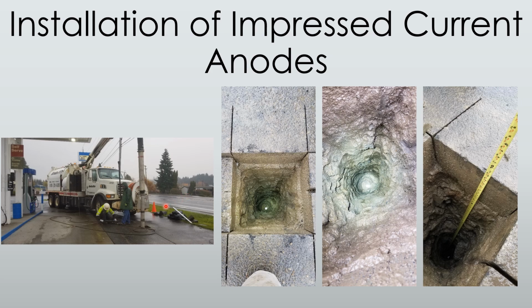So once you're through the asphalt, you've broken through any kind of random concrete, and assuming you haven't hit any vent lines that were untraceable or any other kind of fun things that were present in the hole, we typically use hydro excavation. Just use water and air to excavate the hole because, again, it's pretty safe. So if you come across a non-traceable utility or non-traceable product pipe, you can just move the hole in the event that you do come across it. This one was clay. It was a great hole example.